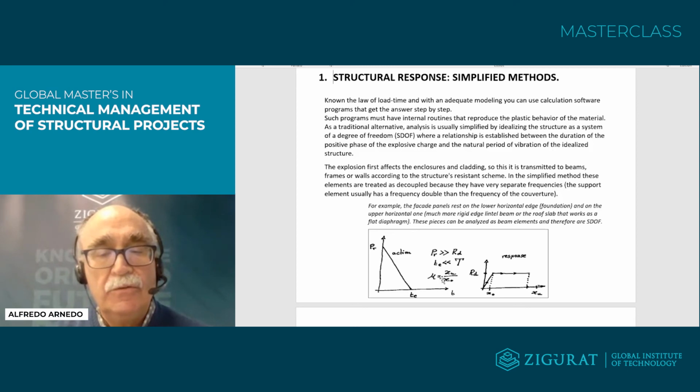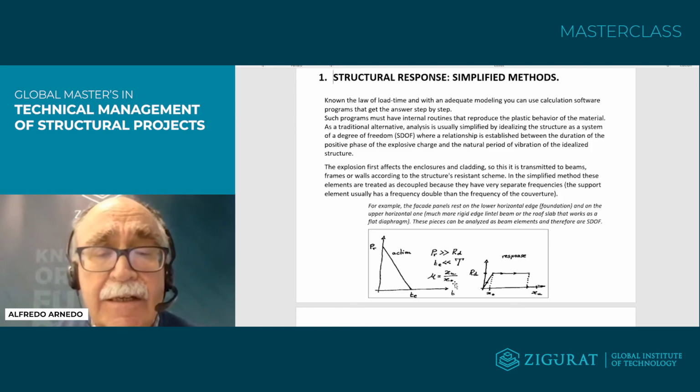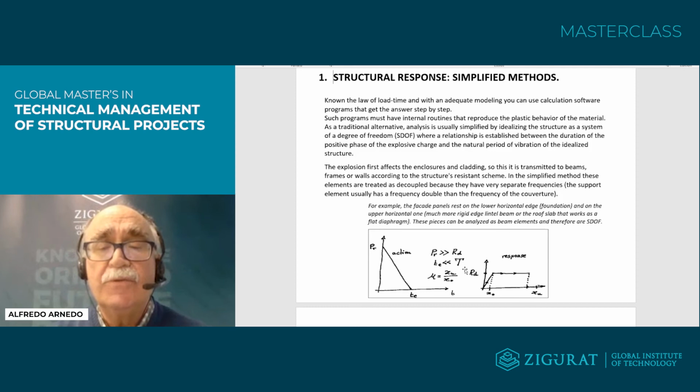This leads us to the concept of ductility, the relationship between the maximum displacement in the response and the linear one. This relationship is, in some sense, more or less the damage that a structure can suffer.